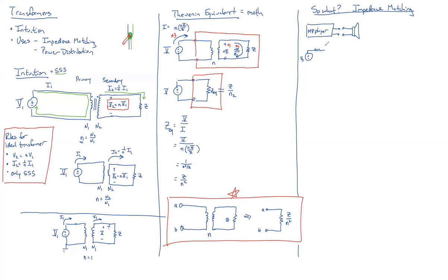So let's look at what that Thevenin resistance is, and just to make the numbers easy, let's say it's equal to 990 ohms, and let's say our speaker is about 10 ohms. And by the way, those numbers are fairly reasonable numbers. So my question is, now that you've put in the Thevenin equivalent, let's find out how much power ever gets to those speakers.